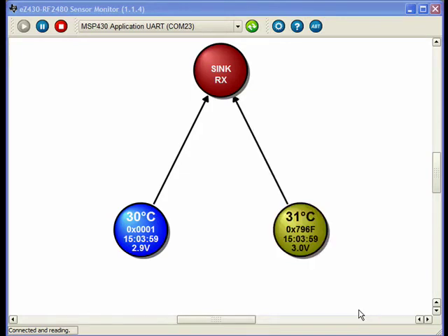both the router and the end device are connected to the coordinator. This will be the case until the coordinator fills up and is unable to take any more children. At that point, you would have children off the router, if the children of the router were out of radio range of the coordinator.